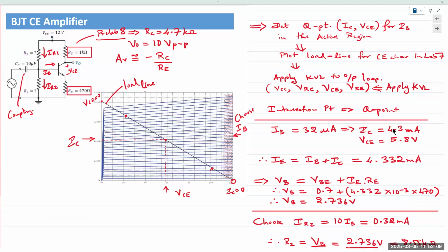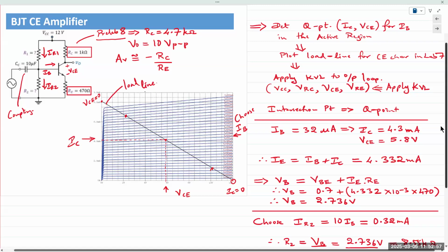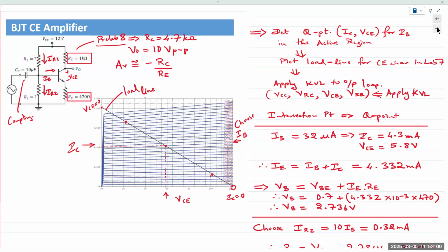And so you have 2 transistors in your lab kit, same manufacturer, same model, but the betas might be widely different. What was the range? 35 to 100 according to the spec sheet. You might have a 35, someone else might have a 70, or in the same lab kit, you might have 135 and 100. So it'd be wildly different. That's why every student needs to look at the data they collected so they know the beta value for their BJT. And then you use that BJT as a CE amplifier. Okay. All right. So that's the design. That's the pre-lab. That's what you would use.